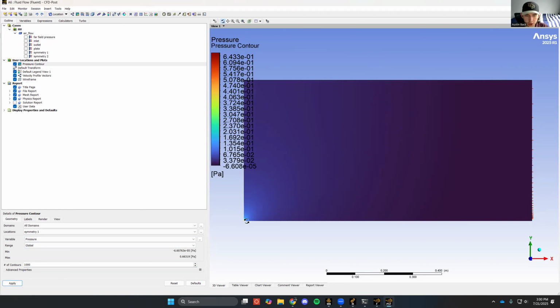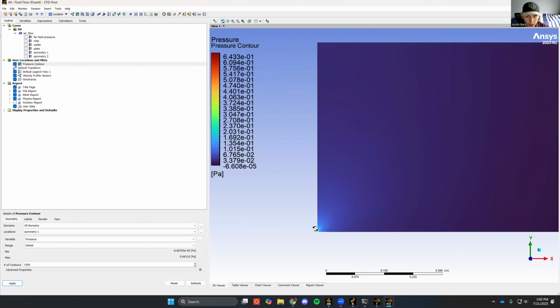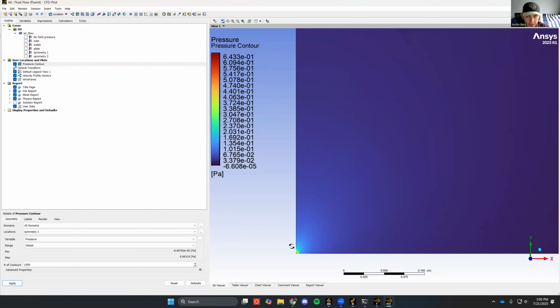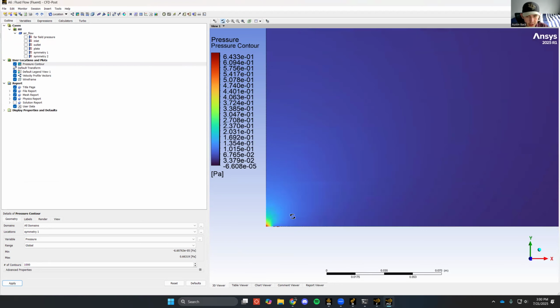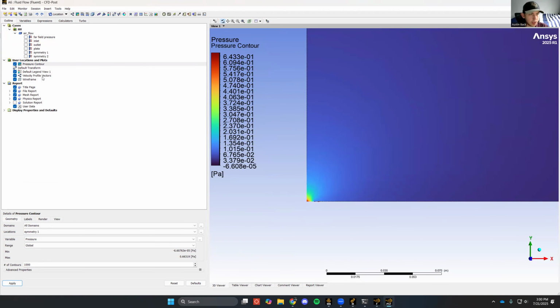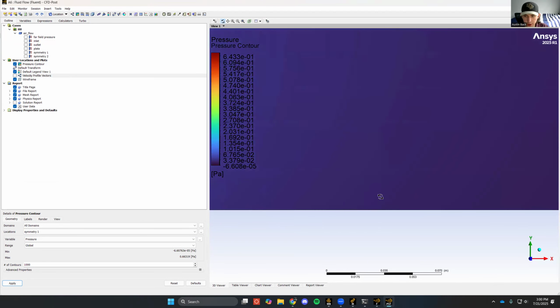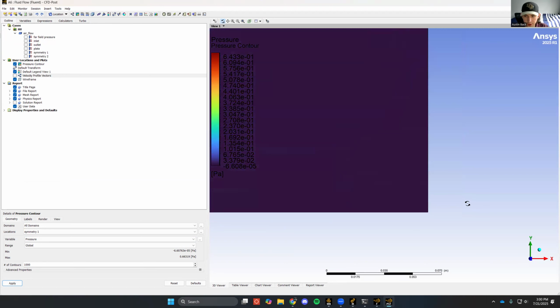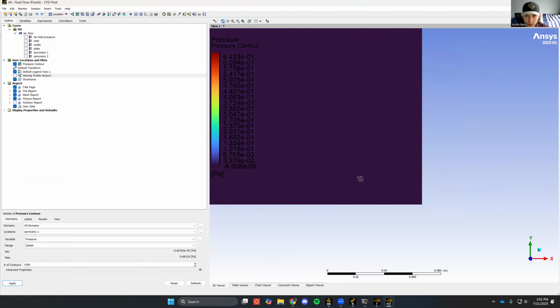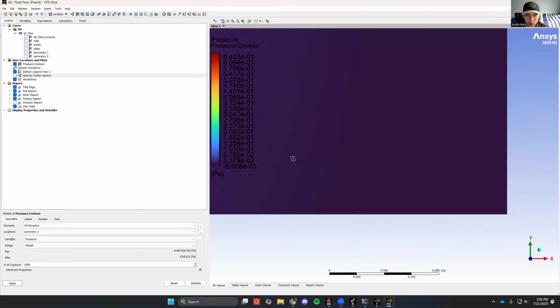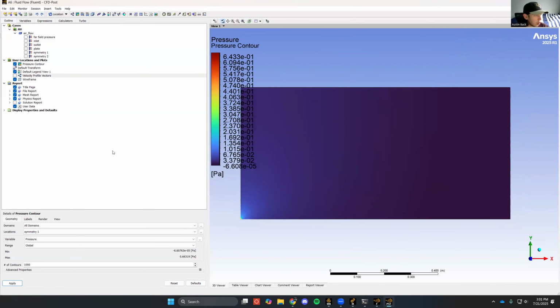You can see the pressure is peaking here right at the start before the boundary layer forms. And this is a good telltale if your mesh is good, because if your mesh is very coarse, you're going to get a larger region of red because you don't have a fine enough mesh. So this being really small is a good thing. And also you can see that red in the background. That's just the velocity profile. We can just hide that, get that gone. So yeah, this is looking good at the boundary layer. As you can see the pressure decreasing as you go along. Looks very good. Okay, also yeah, it does that sometimes. So let's scroll way back out, get this centered. All right, so we got those.